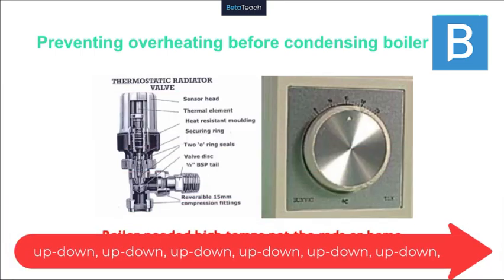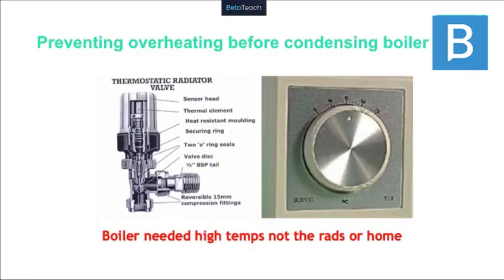Now, to save you doing that, something can do it for you. That was what the wall stat was about. These devices were not introduced as energy saving devices. They were introduced to turn the heat off because we were constantly overheating homes. Same with the TRV. TRVs were not introduced as energy saving devices. They were introduced to shut them radiators down. You might have had your children in the bedroom, you're still up watching telly. You didn't want your bedrooms overheating. So this is why these devices were introduced. The control industry is very, very big around Europe, and I think they may have forgotten why their own technology was actually invented in the first place.